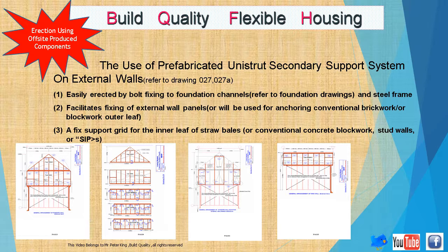The use of prefabricated unistrut secondary support systems on external walls. Easily erected by bolt fixing to the foundation channels, referred to in the foundation drawings, and the steel frame. This system facilitates the fixing of external wall panels and the inner leaf blockwork.